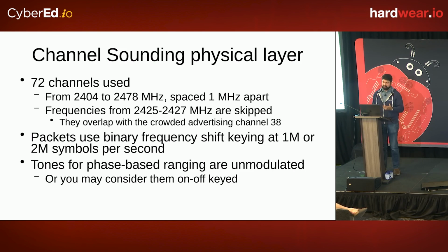For phase-based ranging, it just transmits unmodulated tones at these frequencies at certain times. There is a portion of the tone where transmission depends on a pseudorandom bit. That portion of the tone may or may not be transmitted depending on the value, so you can think of that piece as an on-off keyed portion of the tone.